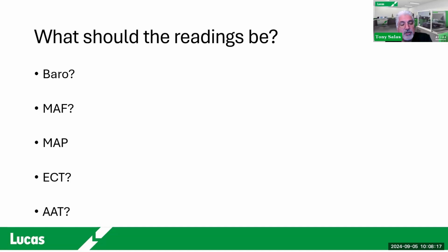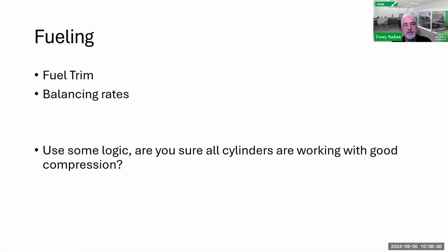And then we've got our engine coolant temp. I haven't said enough about that yet, right? Engine operating temperature along with ambient air temp. So use a little logic, because a lot of guys tend to forget about logic. Okay, I'm taking a minute. I'm going to scroll down the list, see if everything is where it's supposed to be. And guys, when I step into a shop and they want me to look at a truck, I follow that same sequence of events, because, okay, what are the inputs that the computer is getting? What are these PIDs telling me? Because I cannot look at fueling if I don't know what those sensors are at.